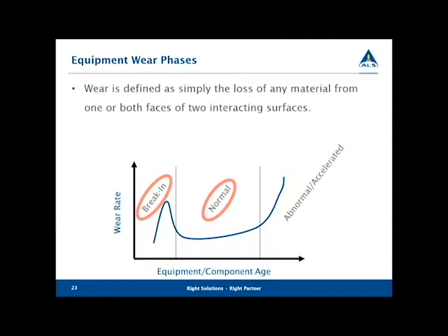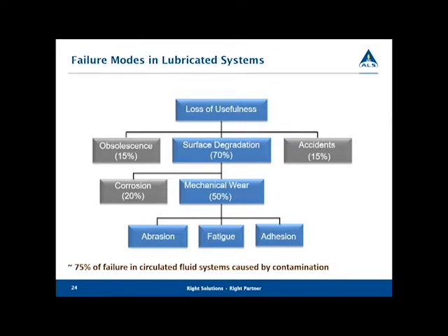That's really normal wear. Now, the abnormal accelerated wear, that's attributed to overtaxing the asset, but it's also attributed to contamination and eventual lubricant breakdown. We're going to talk about that here in a minute. Now, as we spoke about earlier,